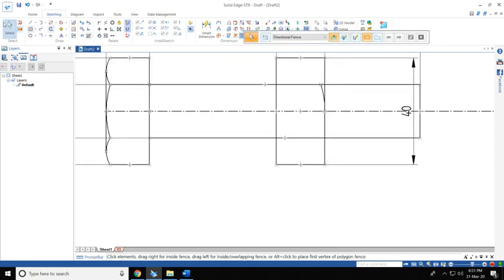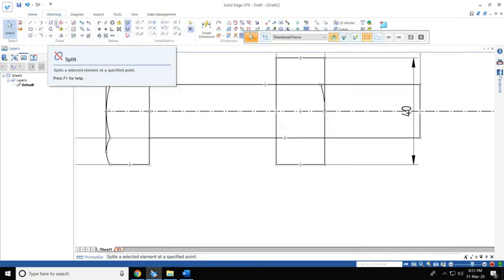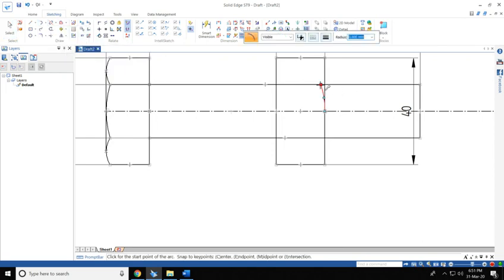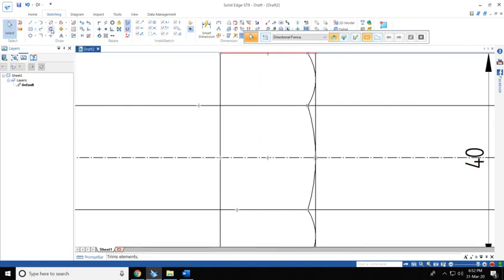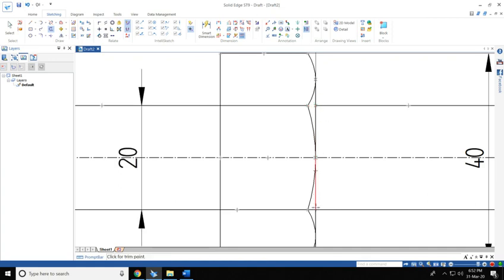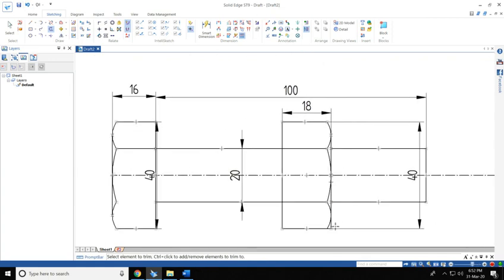I remove this line and again arc by 3 points, touch here and then straight upward and then here. Now select both of it, mirror the feature about the axis. Done. Next would be trimming the unwanted here, here, and this line, and here, here. Okay.